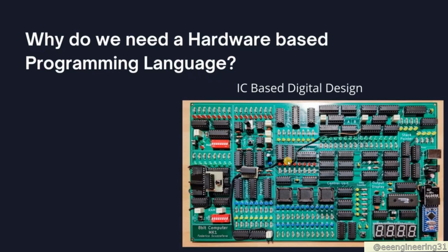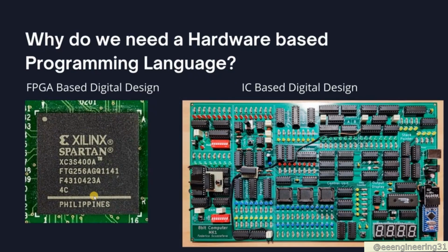That's crazy. However, what we can do is throw all of this away and just get this small chip, which we call an FPGA, or Field Programmable Gate Array. We will throw all of this away, and we are going to program every one of these black integrated circuits inside here. So we are going to define AND gates, latches, ALUs, memory sections. We can do whatever we want, and we can pack any digital system we want inside here.